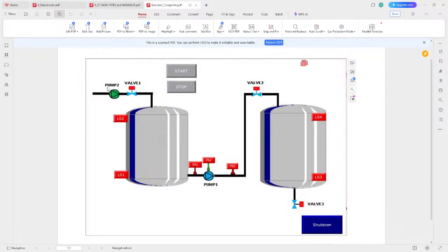Pump 2 comes on, then after 5 seconds, the valve comes on. And when the valve is on, it pumps till it gets to LS2, level switch 2. All level switches are normally open, so let's not mix it up. Once it gets filled up to LS2, it stops the pump first, then the valve. It takes 2 seconds, after which it stops the valve.